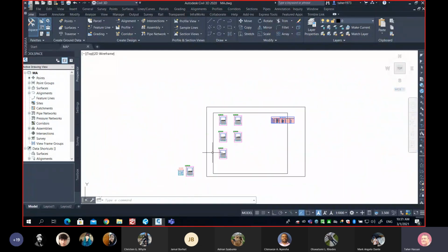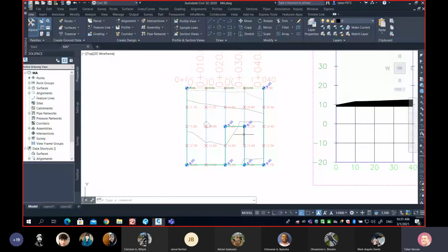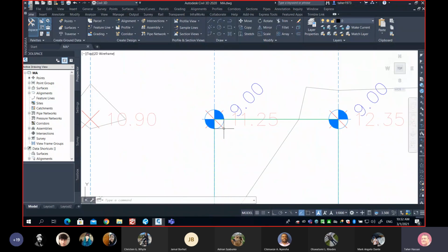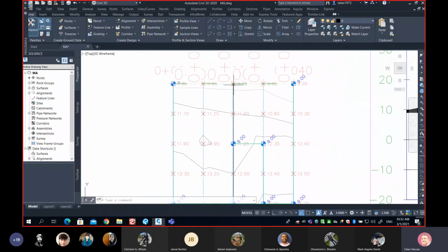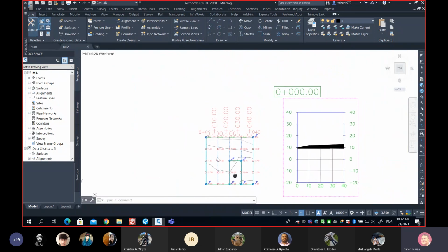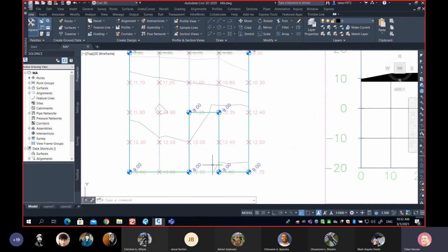How about the plan view? So let's look at the plan view. The software simply took your cross-section area, which is exactly at 20, but the problem is there is a building. So the software got this big area from here to there and took the average between this area and this area here. And what does this mean? It means you have demolished the building, while the reality is the building is to stay, and we need to account for that.